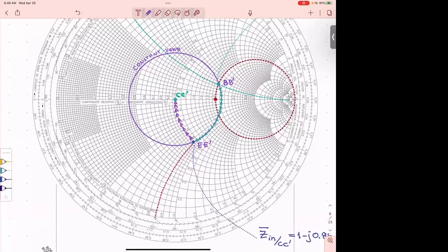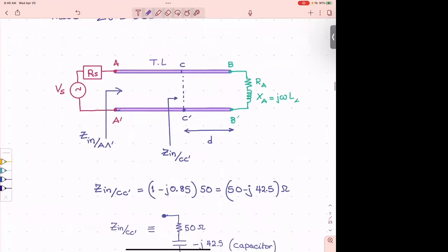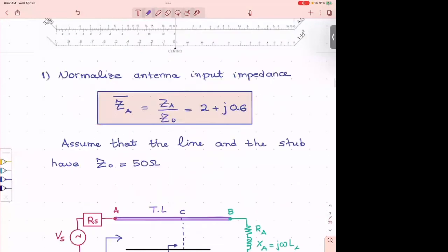Also, you need to remember, if I ask you, without Smith chart or anything, how much is the input impedance when D is half a wavelength? What are you going to tell me? No, 0, please. Yes, thank you. Z_L in half a wave, every half wave. If I tell you that D is a wavelength, how much is that? Z_L. Still the same. If it's 3 half wavelengths, still the same. So every half wavelength repeats. It's easy to see it on the Smith chart.